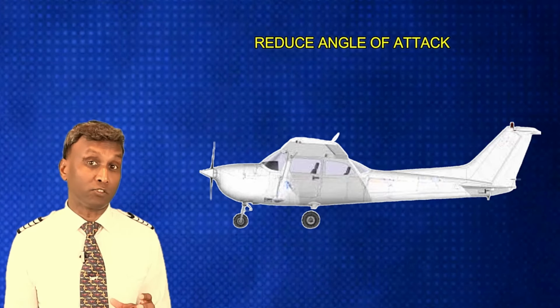The good news is, pilots are trained to deal with stalls. To recover from this stalled condition, the nose is lowered, the angle of attack is reduced, and power is added. This helps the air flow smoothly over the wings again, and the wing produces lift with the aircraft flying smoothly again.